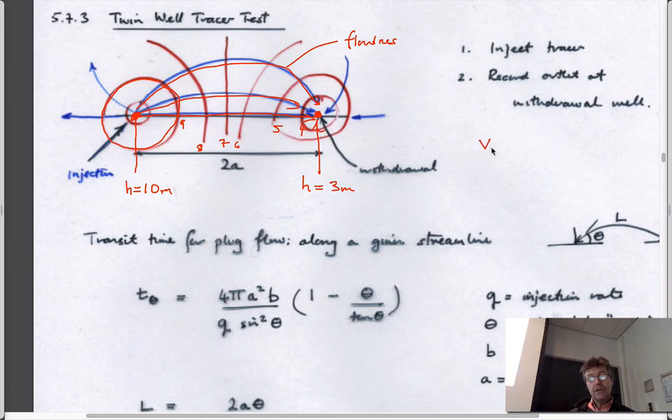And so since we know that advective velocity is equal to hydraulic conductivity, porosity, and head gradient, then if the head gradients get smaller, when these other two parameters as material properties stay the same, then this is going to go down. And so if you look here, this head gradient here has to be larger than the one here.